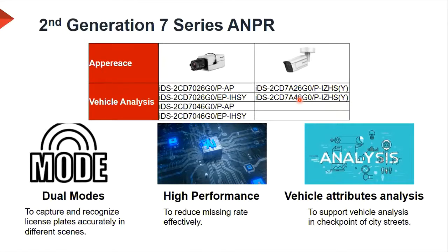If you go higher than 4.5 meters, you'll see that you go over the 30-degree restriction if you look at the vehicle number plate's distance away from the camera. That's why we say stick to these distances, and you cannot really go wrong then. I hope that was helpful.